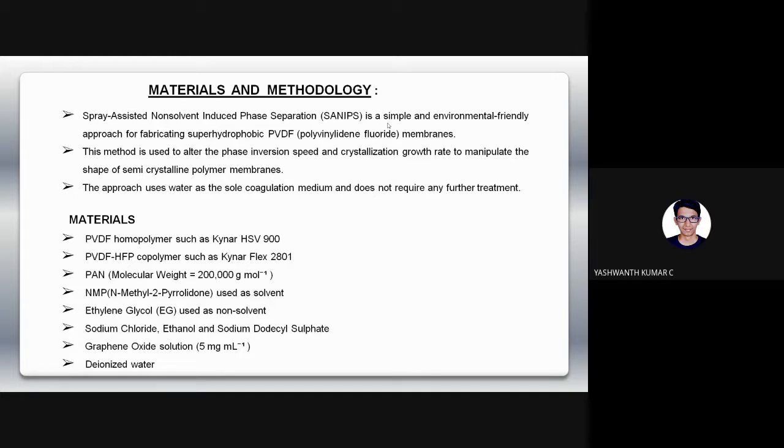Here, we describe how to use the SANIPS approach to create superhydrophobic self-cleaning PVDF membranes with high porosities and configurable multi-level roughness. The spraying step causes not only quick partial surface solidification but also local membrane surface deformation, resulting in the first level roughness. When the nascent membrane is introduced into water coagulant, the newly produced skin will obstruct the solvent-non-solvent exchange, causing delayed demixing and the development of second level of roughness. Further, various spraying materials can be used to adjust membrane morphological structures.